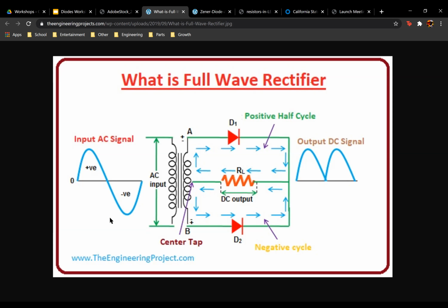When this flows through, we'll get a positive DC signal all the way, because this portion comes in through here and gives us that, and this negative signal portion comes in through here and goes through our diode. This is our second wave. So this is called our output DC signal, because normally we would have our load resistor experiencing our DC output.